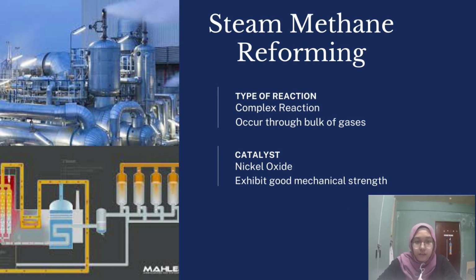The objective of reaction engineering in this project is to propose a suitable type of reactor and catalyst used in the reaction. For the SMR and WGS reactions, both use a packed bed reactor (PBR). The SMR reaction is a complex reaction. Diffusion of reactants occurs through the bulk of gases to the surface of the catalyst and porous particle.